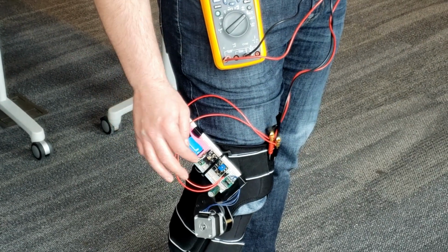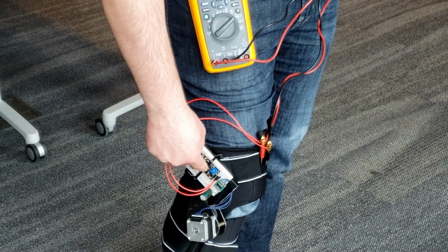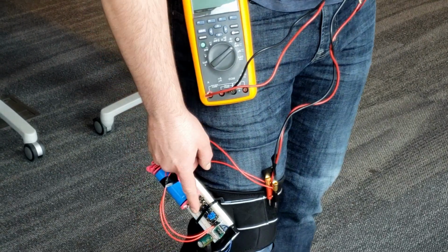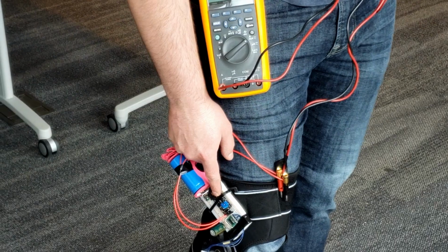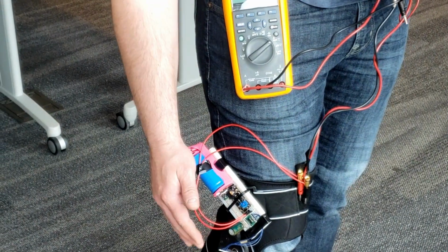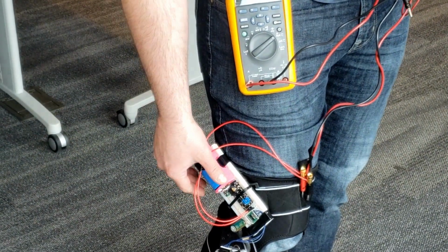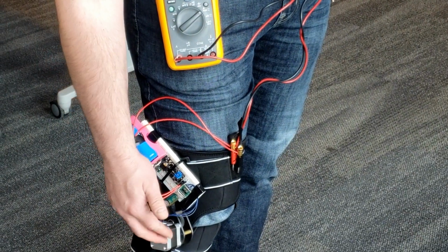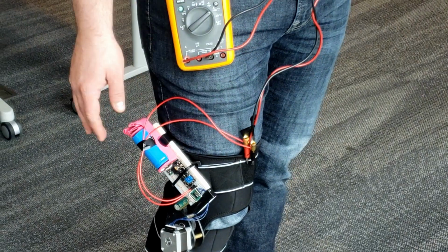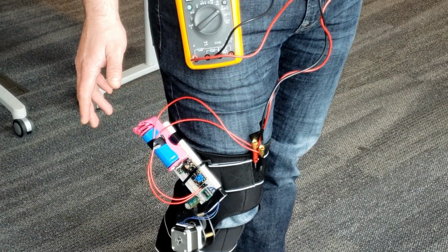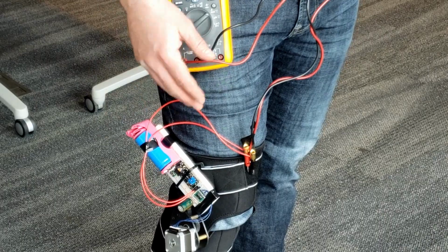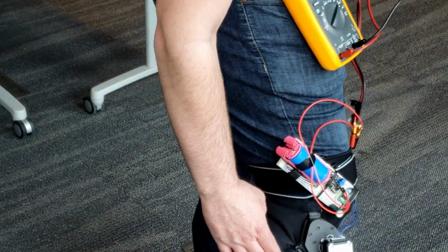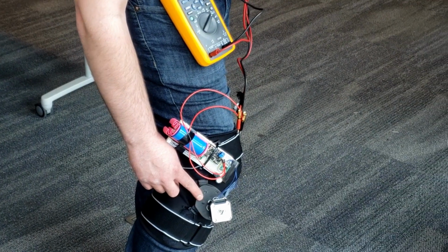Now the interesting thing here is we again use a solar charger here, because it turns out the maximum power point tracking algorithm really helps to regulate the negotiation between how much of a load is felt here, I should say output impedance, and how much is felt by the generator here. And it turns out we can actually have a significant increase in power output, or I should say power efficiency of this generator system.